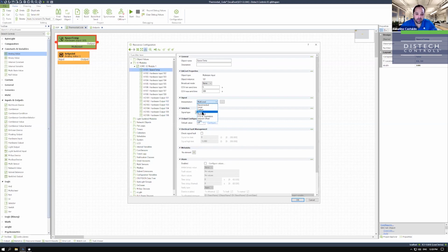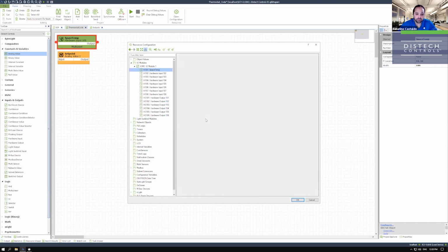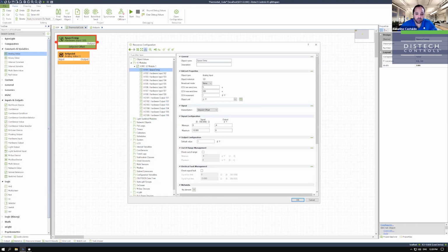All right, digital multi-level. We saw thermistor set point offset. This is another type. You then tell it what signal you're receiving, and you give it the min and max of that signal interpretation. So 0, 10K, -4 plus 4. You just put a negative there for -4. I'm sorry if it's small. This is the biggest size I can make it unless I change the resolution of my screen. But that's pretty much how you would set up your set point offset.